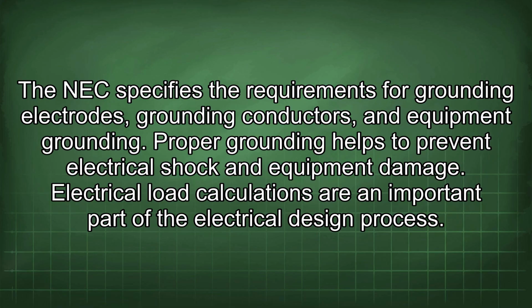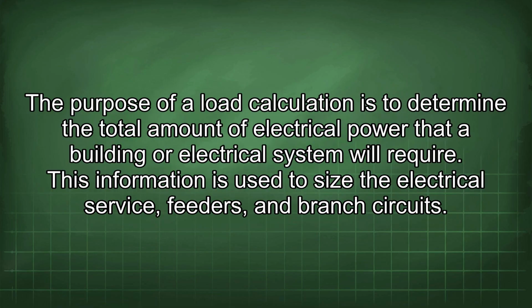Electrical load calculations are an important part of the electrical design process. The purpose of a load calculation is to determine the total amount of electrical power that a building or electrical system will require. This information is used to size the electrical service, feeders, and branch circuits.